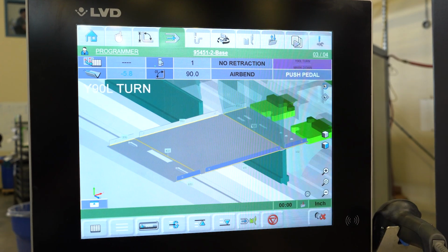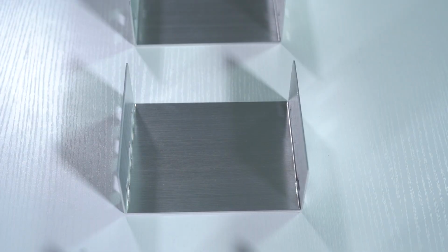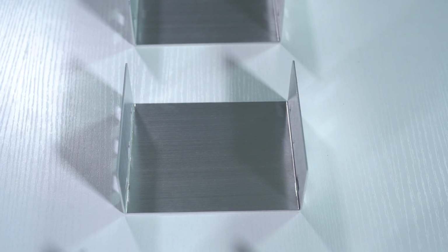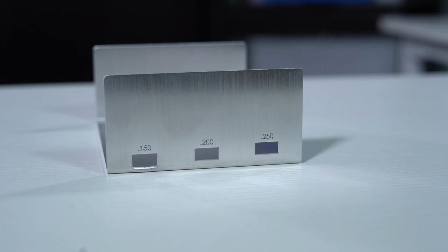Cutout positioning is one of the earliest decisions in a design process, and a misstep here can lead to a lot of problems down the line. A common mistake is placing cutouts too close to bend lines. When the sides are being bent on our press brake machinery, cutouts can stretch or flare. This can be a problem, especially if you need to fit a component inside the cutout. Therefore, you should consider the minimum flange value, which is the minimum distance the edge of a flange or specific cutout can be from the bend.